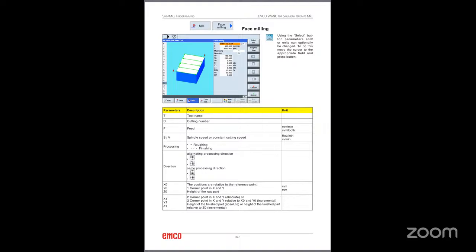It is a block, so it's 00, it's 100, 100. HA is the top surface, HI is 24, retraction plane 25, and safe distance 2. Machine sequence, this one, that's it. Everything is okay.